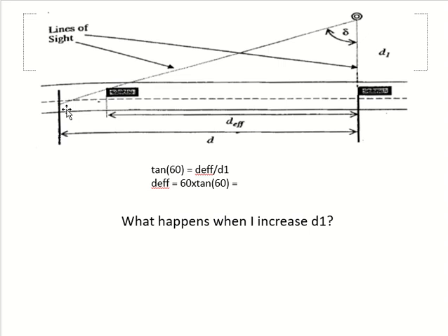To get the speed, I should do distance upon time, but I can only do distance upon time if the distance and time both are matching. If I know the exact distance which is covered by the car in this much time which I have recorded. So in 8.3 seconds, how much distance has the car covered? It has actually covered this much, d effective. d I know is the trap line, which is 400 feet. The observer has fixed it, but d effective I don't know.